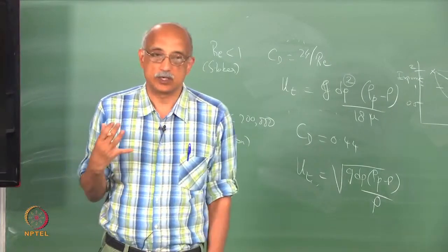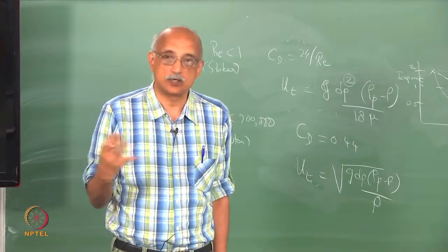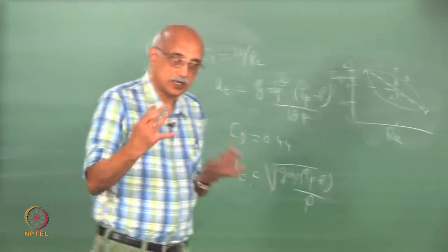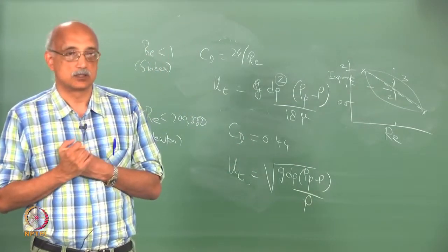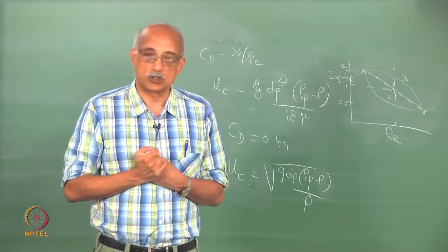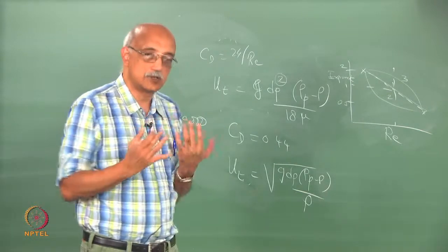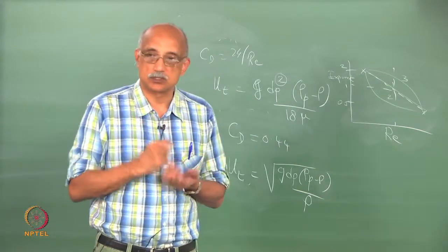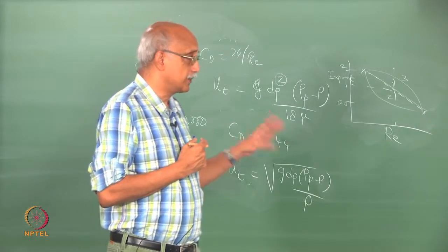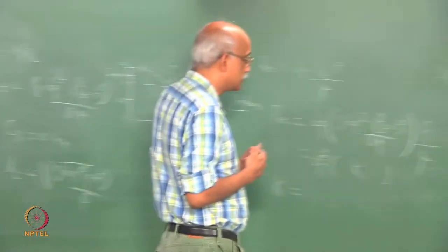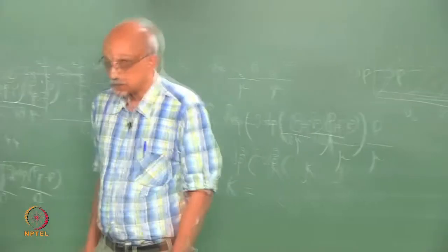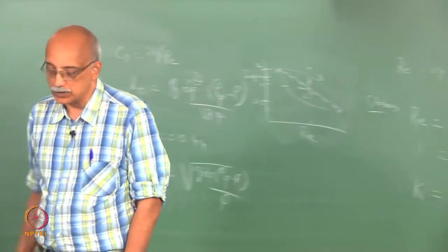Particle motion in a fluid wants to reach a steady state equilibrium, and therefore there is actually a driving force. The farther away it is from an equilibrium condition, it tries to proceed to that equilibrium condition faster. And so the transient behavior as it tries to approach this equilibrium is quite strong. So the basic behavior of a fluidized bed, particularly in terms of its pressure drop characteristics and expansion characteristics, is something that we should look at closely.